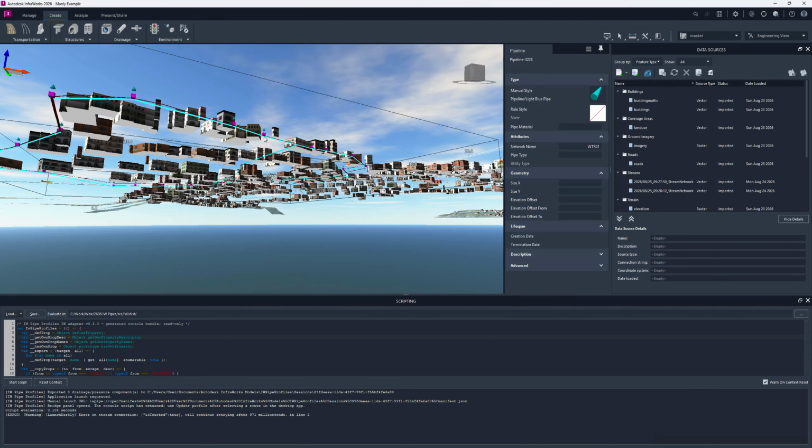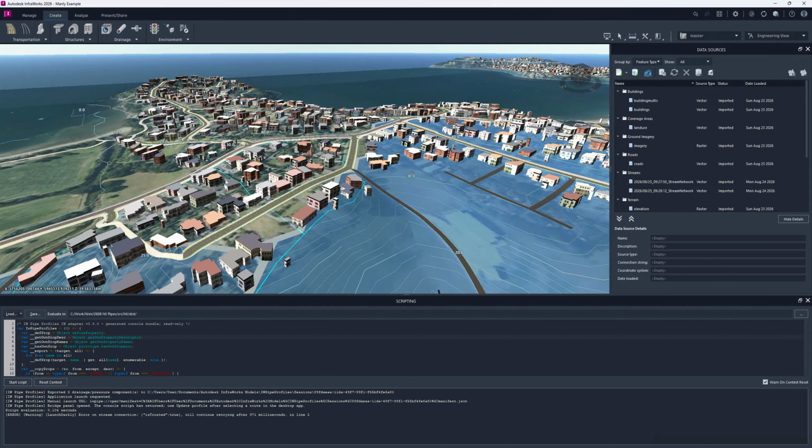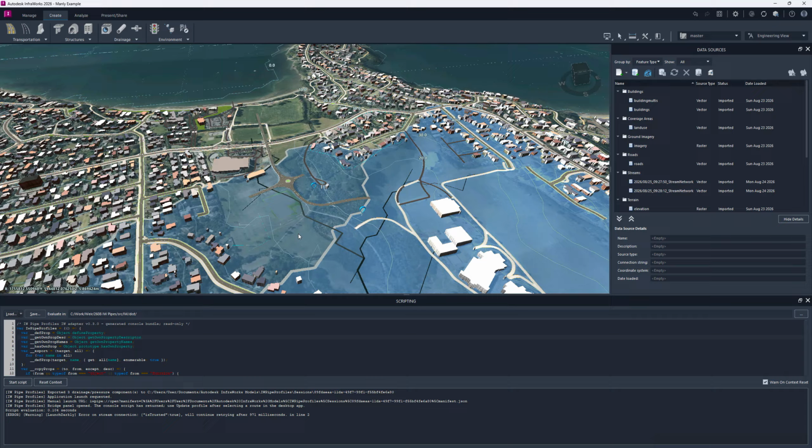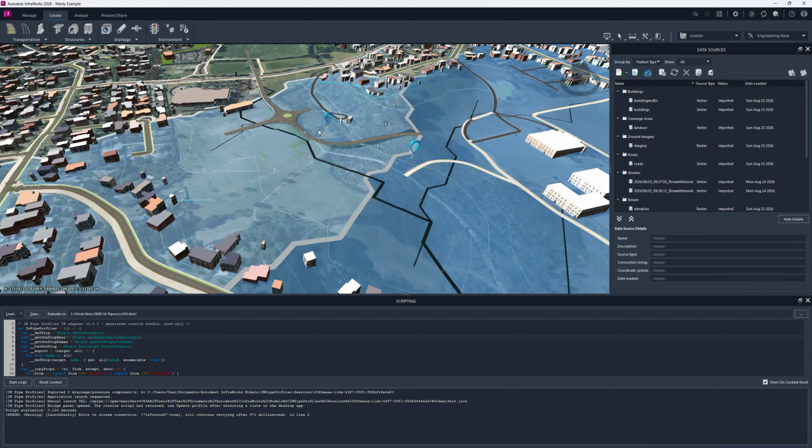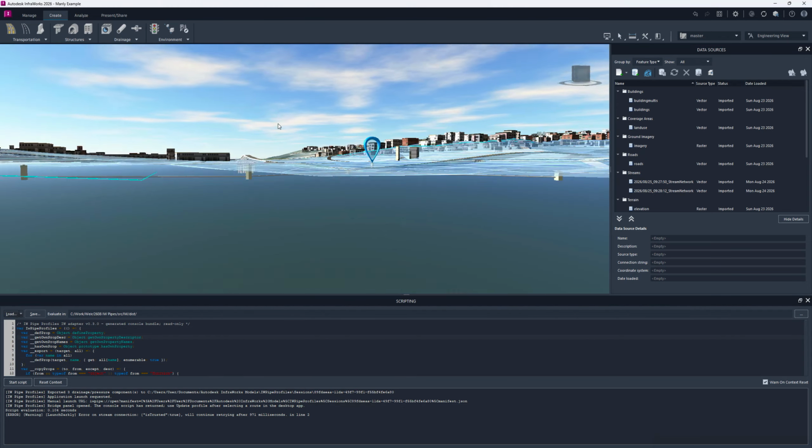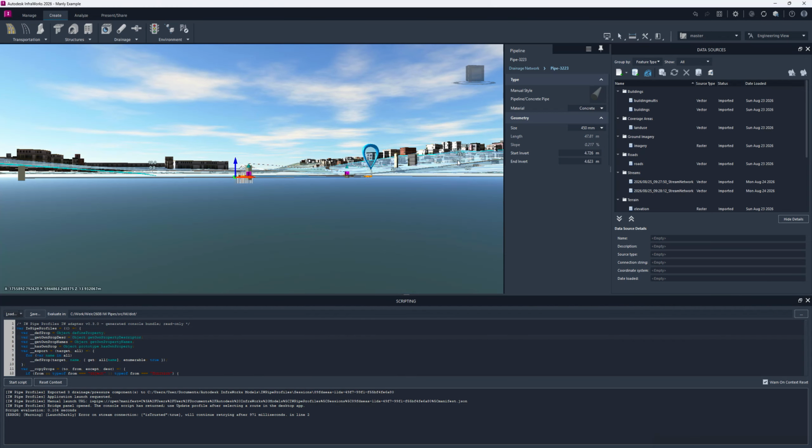The only thing they've really got is a size, which I've left blank here, and then obviously the pipe start and end node elevations or invert levels. So I created this drainage network, and if I select any of these elements, you'll notice they belong to a network. So there's my drainage network.